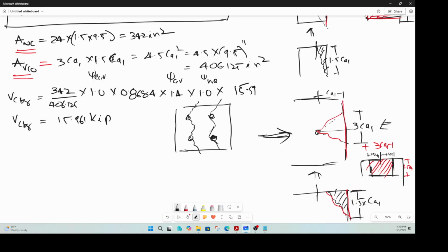But once this fails, this will lose meaning, correct? So once these two fail like that, this will lose meaning. So the limiting shear strength is just 2 times of. So for the group, that is the factored, nominal shear for the group of 4 bolts is 2 times the capacity of these two, right?